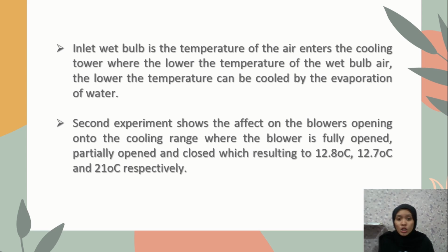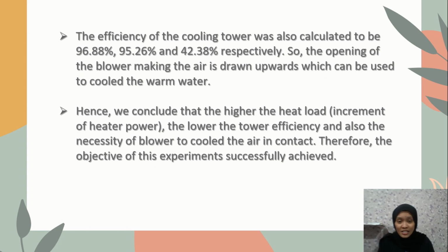So the second experiment showed the effect of the blower opening on the cooling fluid, where the blower is fully open, partially open, and fully closed, resulting in 12.8 degrees Celsius, 12.7 degrees Celsius, and 21 degrees Celsius respectively. The efficiency of the cooling tower was also calculated to be 96.88, 95.26, and 42.38% respectively. So the opening of the blower makes the air drawn outward, and it can be used to cool the warm water. Hence, we conclude that the higher the heat load increment of the heater power, the lower the tower efficiency, and also the necessity of the blower to cool the air in contact. Therefore, the objective of this experiment was successfully achieved.